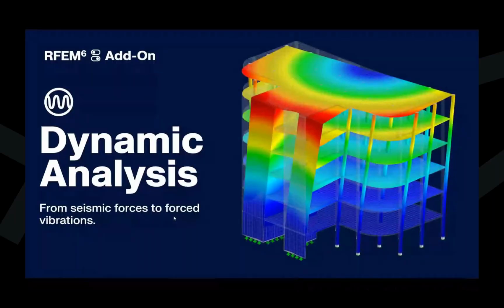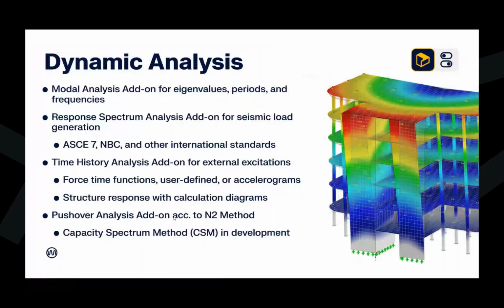Moving on to dynamic analysis. We have several different add-ons depending on the dynamic analysis need, everything from seismic forces to forced vibrations. We begin with our first add-on, the modal analysis. This will take our structure and carry out this eigenvalue analysis to determine the natural periods, frequencies, mode shapes, accelerations. This add-on is always a prerequisite before we can utilize any of the other dynamic add-ons listed here.